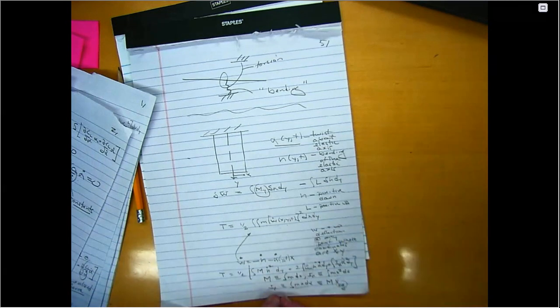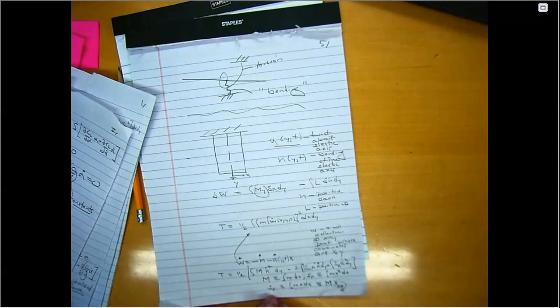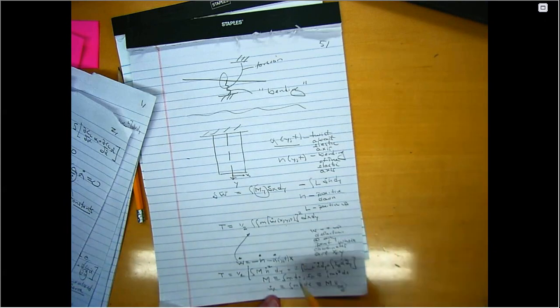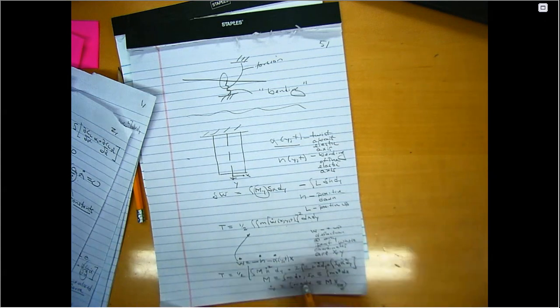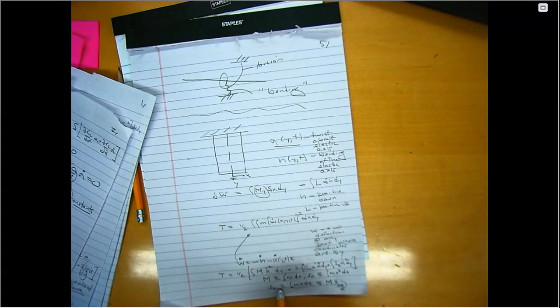Yeah, that's right. It's the distance from the center of gravity at any position along the span to the elastic axis. If the center of gravity is at the elastic axis, then this term is going to be 0. It turns out for this coupled mode flutter, this term is really important. It's one of the most common ways to solve a flutter problem, to change the value of S alpha, as we'll see. We'll see why that's so.